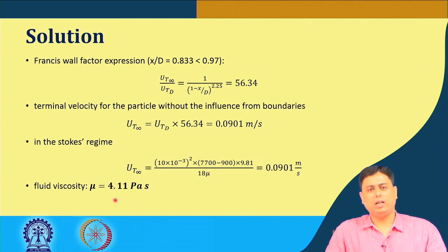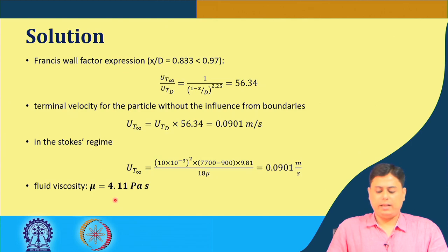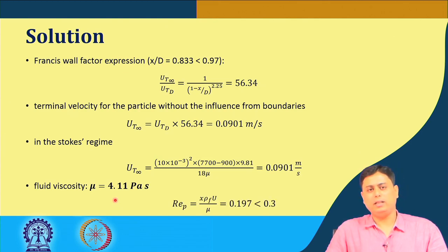Okay, once we convert that, we assume Stokes law is valid, and then in the Stokes law regime we apply that expression and do this calculation. But the point is, we have assumed that Stokes law is valid. So we have to verify that statement.